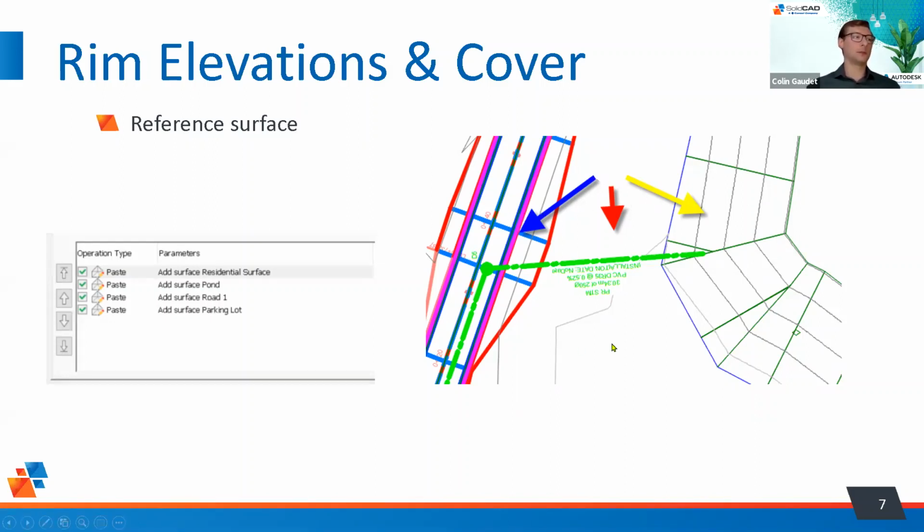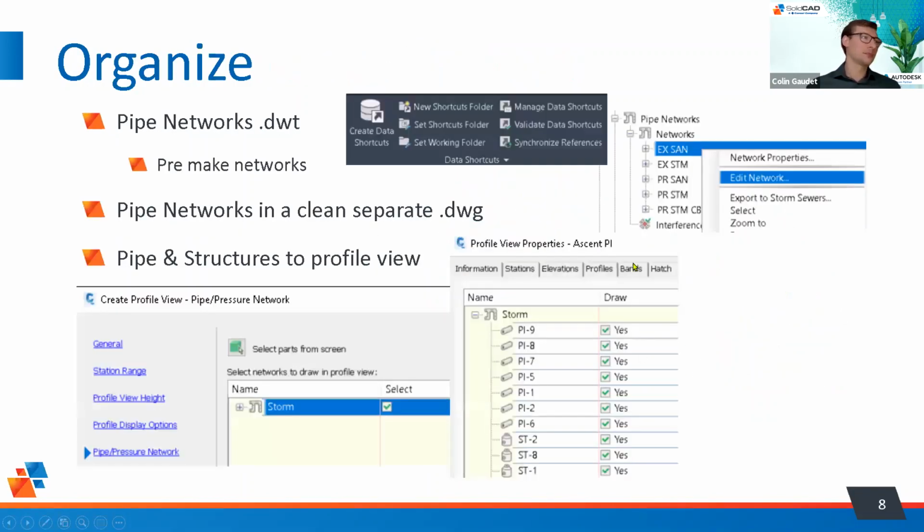It's really helpful to have those composite surfaces ahead of time. And we need to keep organized with it so that we're not fiddling around with that in the same drawing as all of our pipe network stuff. Pipe networks represent pretty big Civil 3D objects. And as a result, they take a lot of computing power in a drawing.